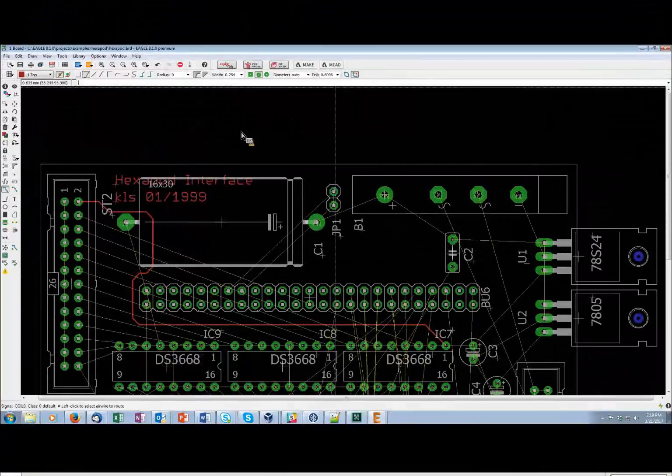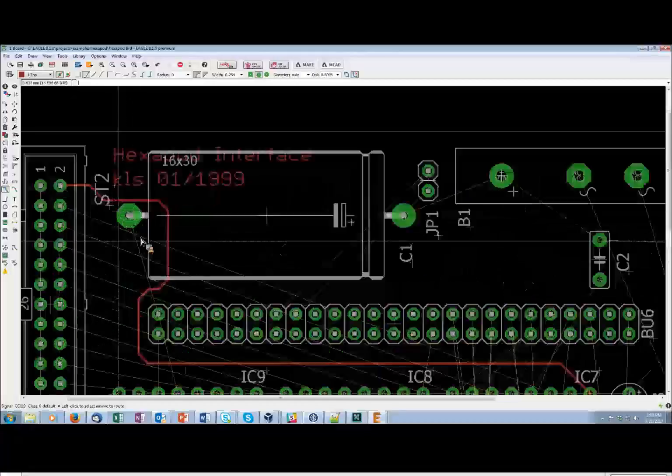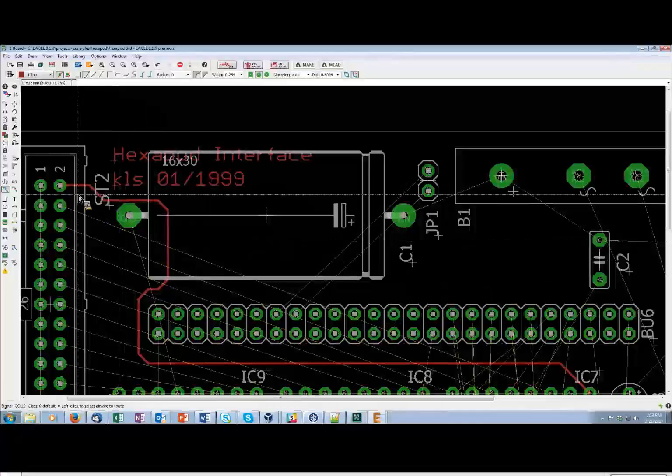Now, loop removal is going to have certain situations where it won't remove a loop. For example, if you have a T junction where you have three traces crossing at each other, at that point the loop becomes ambiguous, so it won't automatically remove it. So let me turn it off to create this issue.